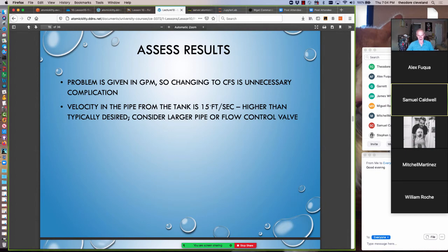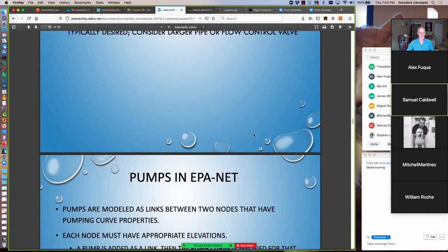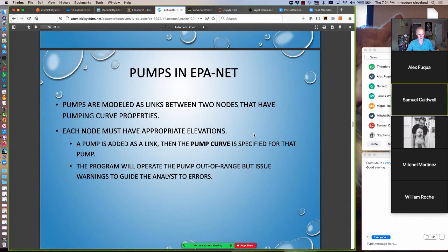These higher velocities are problematic when we have to change the pipe flow direction, because there's going to be a lot of momentum in that pipe. And if you recall, momentum is the product of mass and velocity. As the velocity gets too big, the amount of force required to keep a pipe from moving is fairly substantial. So we have pretty large thrust blocks in these high flow rates. Plus, if the pipe does fail, that's quite a bit of water coming out real fast. So you have trouble drinking it up and cleaning up the puddle.